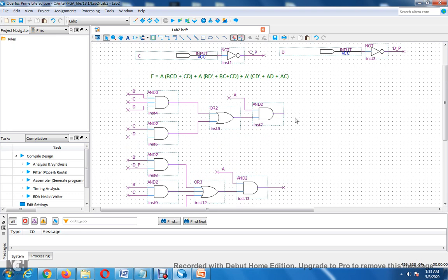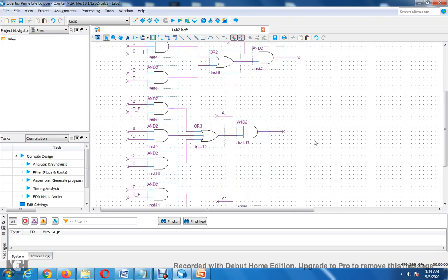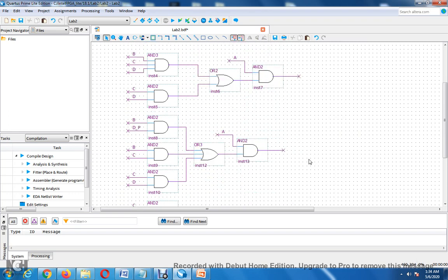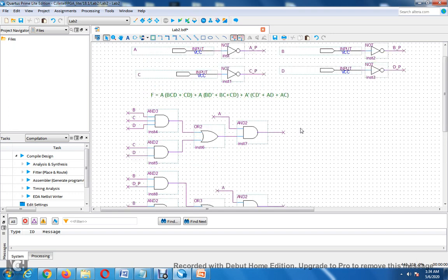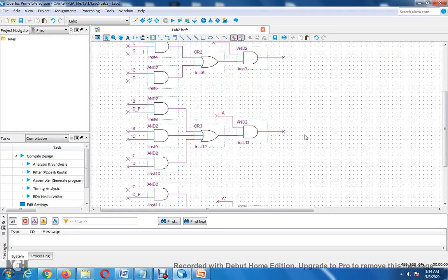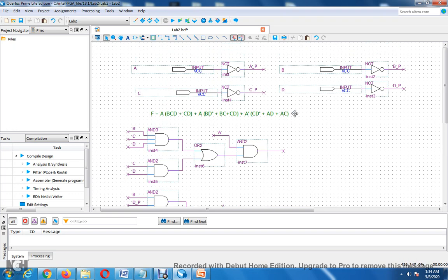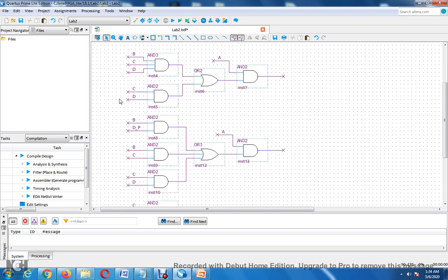Okay, so notice I got three things here. This one doesn't have a wire. No, I can't have a touch in there. It's no good. Okay, so these three things got to get ORed together. Well, I know my problem. Yeah, so move it in like that. But you don't want to have it touching the box. So we got three wires looking to connect up to something. So those three major terms got to be ORed together with a 3-input OR.